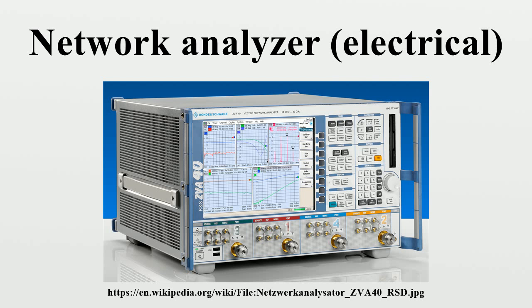Another category of network analyzer is the microwave transition analyzer or large signal network analyzer, which measures both amplitude and phase of the fundamental and harmonics. The MTA was commercialized before the LSNA, but was lacking some of the user-friendly calibration features now available with the LSNA. Architecture. The basic architecture of a network analyzer involves a signal generator, a test set, one or more receivers and a display. In some setups, these units are distinct instruments.